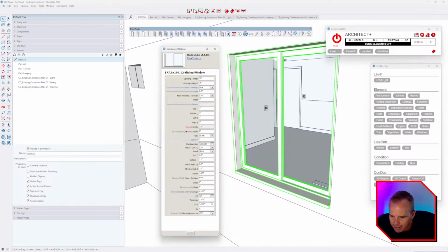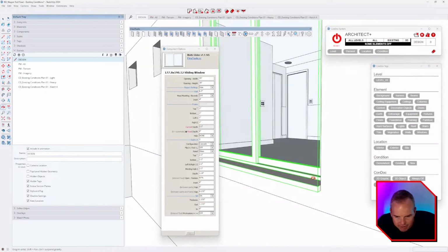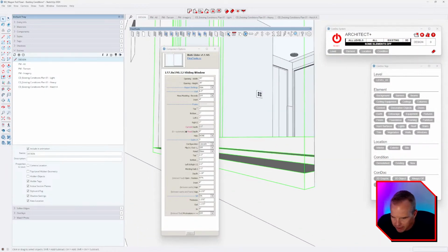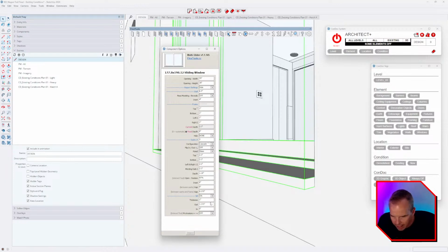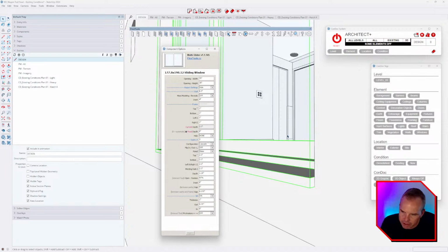And then our sill thickness, I find that to be just a little bit thick, so maybe I would knock that down to 1, and then maybe it goes out by 0.75. But this is where you could go look at the spec sheet for the door and get these dimensions perfect, but I don't know that I need it modeled that perfectly.